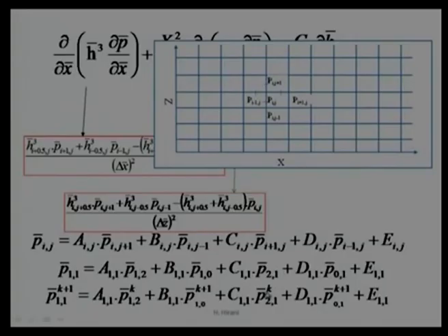So, we take a value which was available from the previous iteration, and coming to the next terms, d 1 1 and p 0 1. Here again that 0 is already over, we have already passed this node, we are advancing. So, this value of the pressure will be known to us. So, it will be k plus 1, that is the recent iteration.